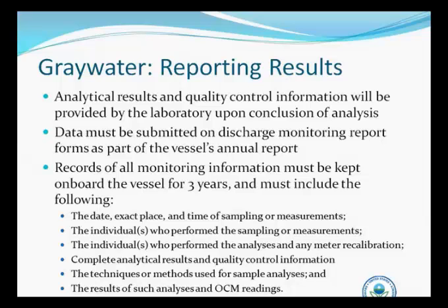In the meantime, any kind of monitoring activities that you do and information needs to be kept on board the ship for 3 years, and includes the following items: the date, place, and time of the sampling or the measurements, the individual who performed the sampling, the individual who performed the test, and any kind of calibration of your meters, the complete analytical results and QC information, any kind of techniques or methods that were used for the testing, and then the results of those analyses and things like OCM readings. So once again, this is where your logbook can also provide that type of information, and it's something good to keep on hand as well.